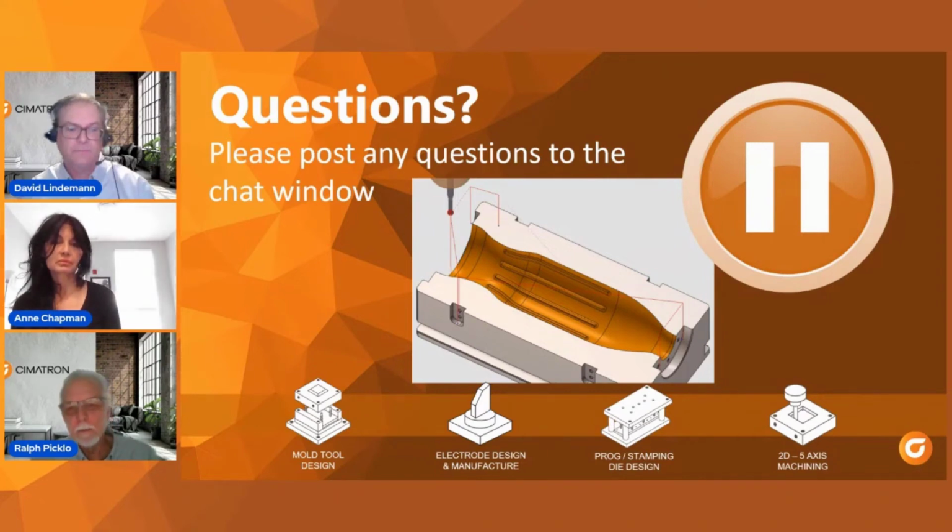I know it's 2/10. Sometimes it matters, sometimes it doesn't, but it went in there and adjusted the wear. So it took the next cut at 5 thousandths 1/10 and took care of the total width being 10 thousandths 2/10 under. So that's how it adjusts the wear offset automatically without typing it in or anything like that.